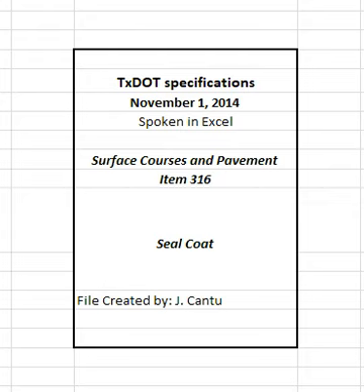3.6 Aggregate haul trucks. Unless otherwise approved, use trucks of uniform capacity to deliver the aggregate. Provide documentation showing measurements and calculation in cubic yards. Clearly mark the calibrated level. Truck size may be limited when shown on the plans. 3.7 Digital distance measuring instrument. Furnish a vehicle with a calibrated digital distance measuring instrument accurate to plus or minus 6 feet per mile. 4. Construction.